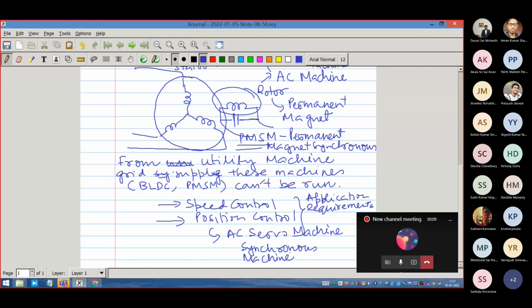However, any machine is ultimately defined by its characteristics of torque versus speed, or more generally, a machine is a torque generator. What is the essential thing that we are expecting from a machine? We are expecting that it will give the certain torque that I require.